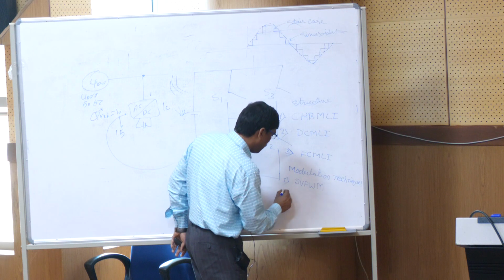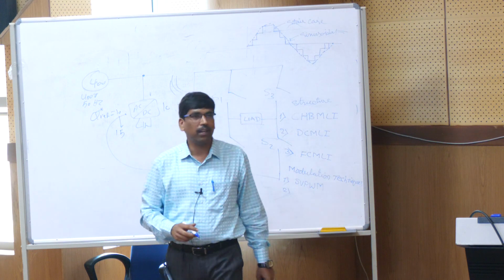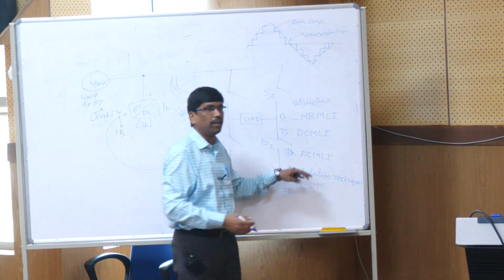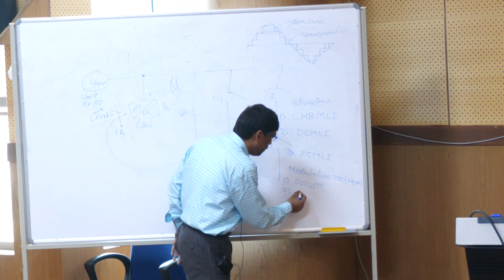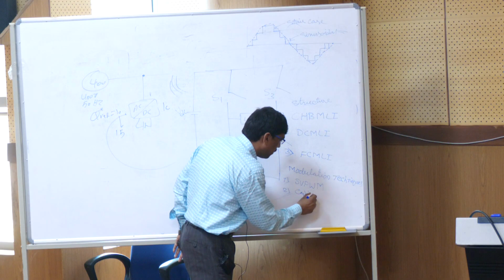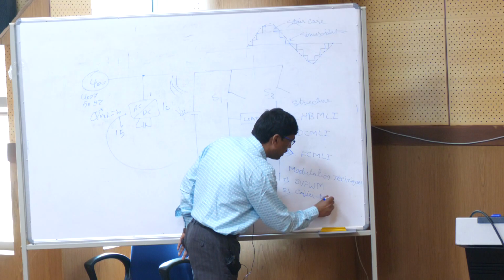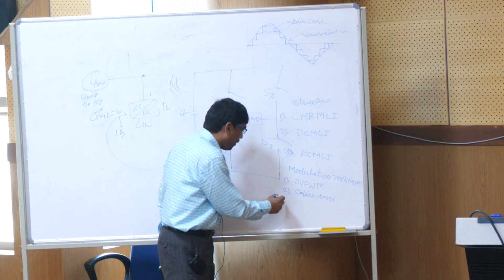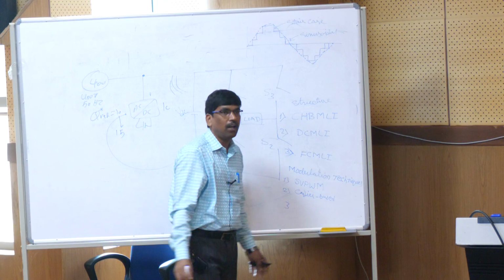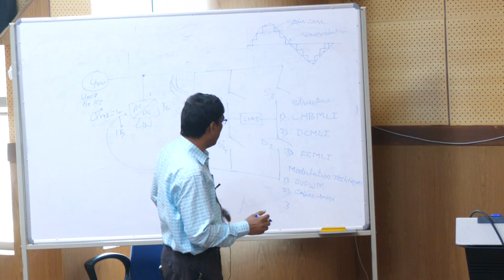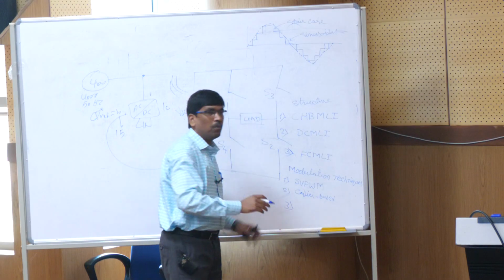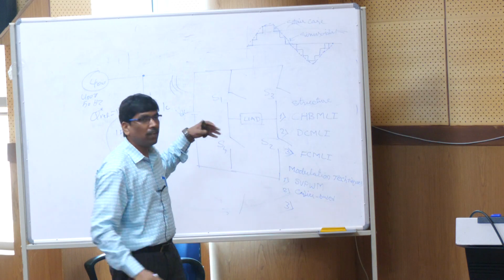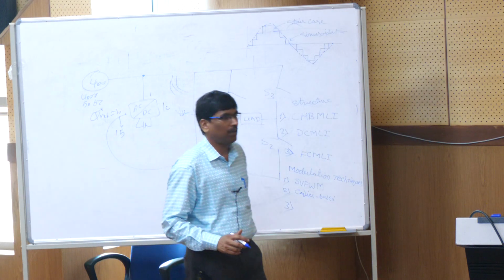Apart from this one, we have the carrier based PWM techniques, and we have a wide variety of classification. One is the carrier based PWM technique, here phase shifted and level shifted PWM, third harmonic injection, optimized selective harmonic injection, these things will be there. I don't want to go more into all these things, just to give some fundamental overview of the kind of topics we are going to have.